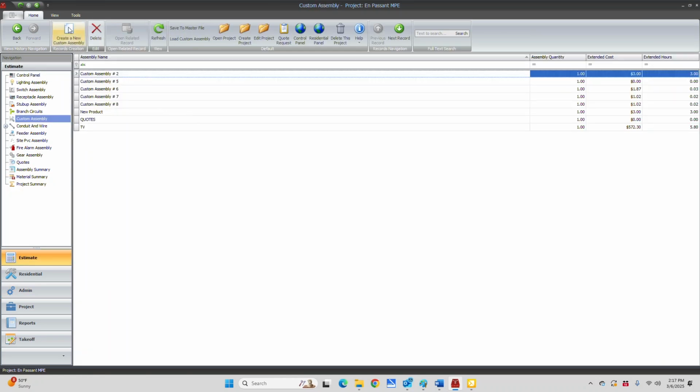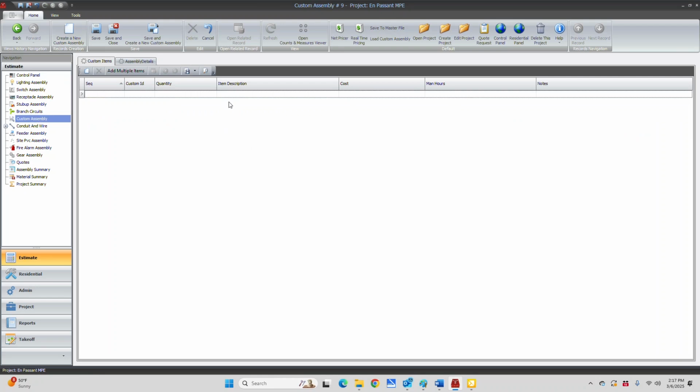And anytime you're on a sheet of paper, you can just go to custom ID, and it'll bring in the product without having to look it up. I'm thinking that C might bring in conduit. Yep. So that's 1/2 inch conduit, 1/2 inch wire. You can make that be quick and easy if you just want to manually bring in some products.